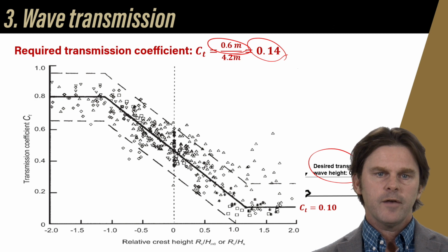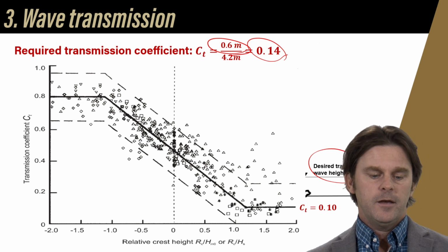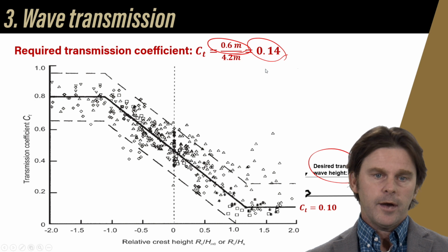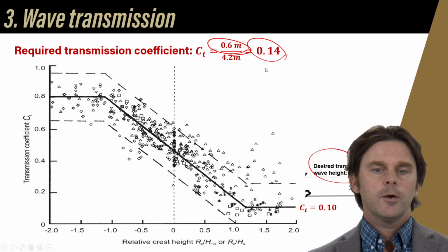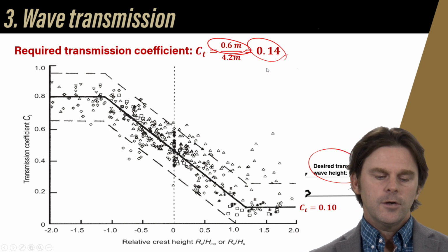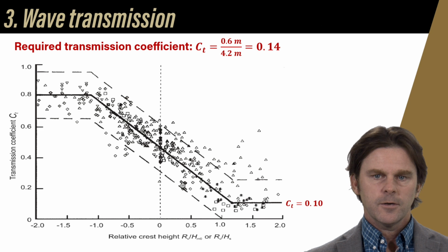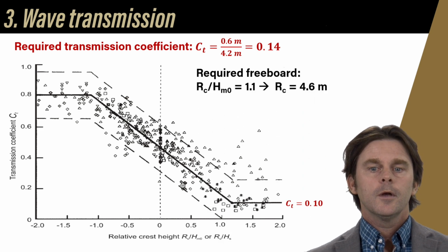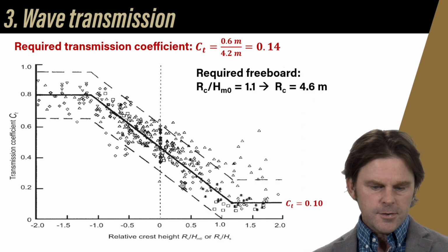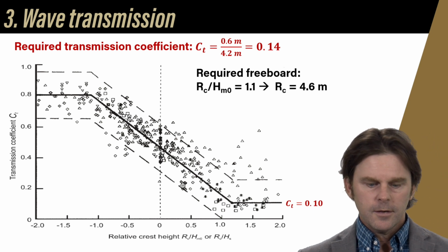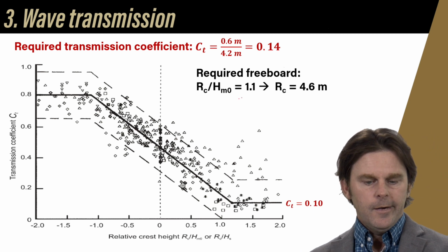Okay, so here's our graph. This is a simplified graph. If you're using this graph, you better be sure that you have a very standard shaped breakwater, nothing funky. And then you're also going to follow up with more detailed transmission estimates from this graph. This is good for getting us started with design. Anyway, that was a big caveat to say don't sue me if your breakwater transmits more than you get from this graph.